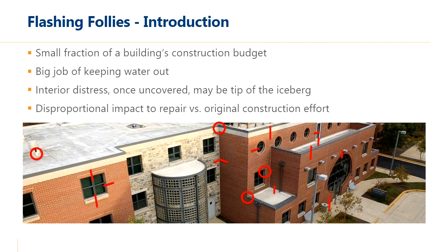So today we're mostly going to be focusing on interface detailing and through-wall flashings in rain screen assemblies, which is where water is meant to penetrate the cladding, travel down a drainage cavity, and exit the wall assembly at different flashing elements that are collecting the water and driving it out. But the principles that we're discussing today and the case studies and what we found and recommend are really going to apply to all different flashing systems, including roofing systems.